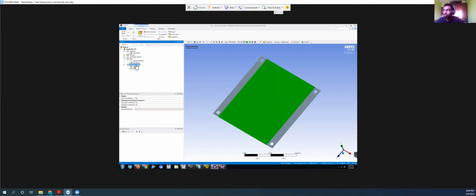One thing that we need to do before we can carry out analysis is split up the model further. So let's say that the center of the panel is 3 plies and the sides of the panels are doubly reinforced, so 6 plies. So how do you indicate that there's a difference between the ply count in different areas of the model? That's where name selections come into play.